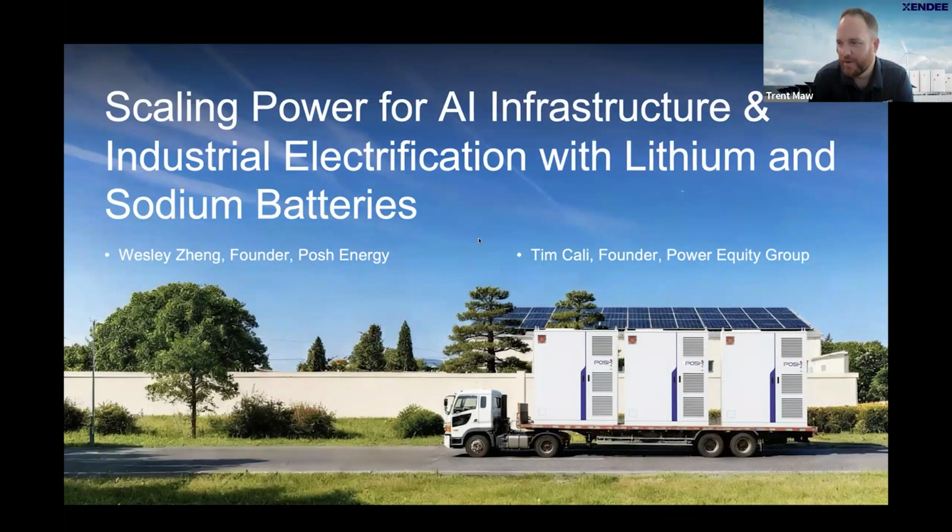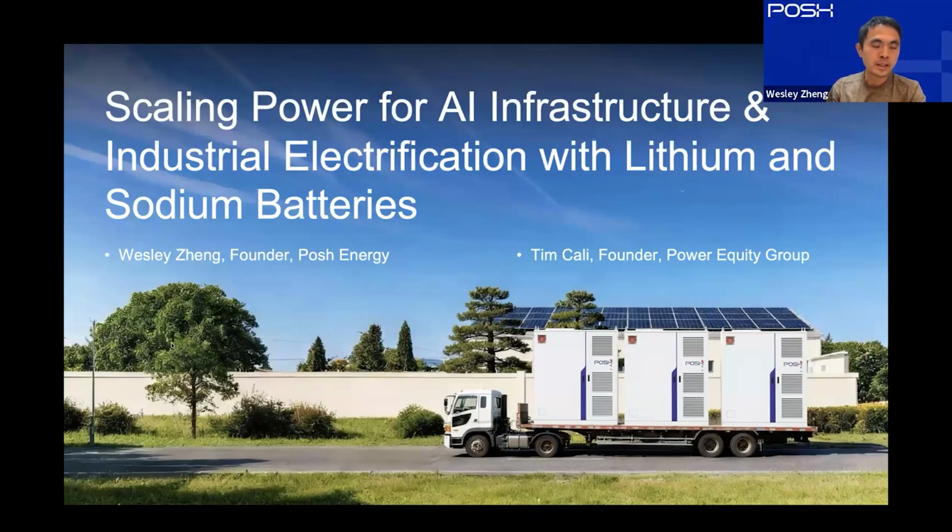We have a really good technical question on the control side of things. Giovanni Gallegos asked regarding the energy management cloud, predictive analytics, does the system combine your AI load prediction models with a dynamic model predictive control framework to optimize battery dispatch under real-time network constraints? Yes. So the AI model is predicting the load profile in real time, and we adjust the charge and discharge and the timing of those events according to the load profile as well.